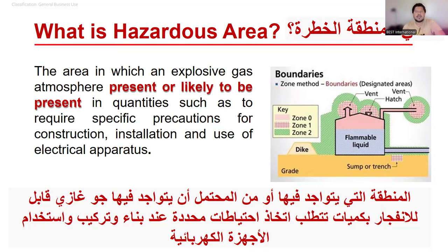Make sure you barricade it and make it color coded. Red color is the right one, so that whether you are educated or uneducated, everybody will understand. Put warning signs there. Let the people understand this is a restricted area, a prohibited area. Nobody should dare to go into this area without a permit.